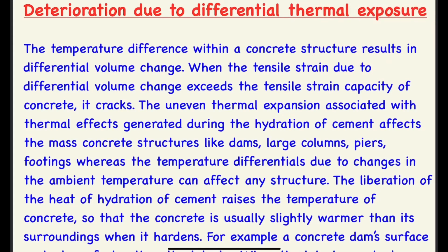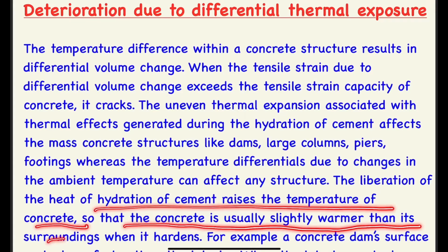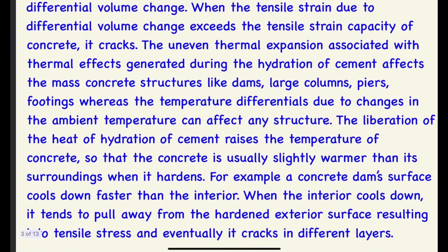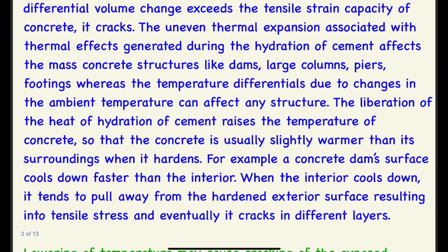So why is it hot? Because the reaction is continuously going on, and it is liberating a huge amount of heat because of the reaction between water and cement. So that is what it is telling here. The liberation of heat of hydration of cement raises the temperature of concrete, so that the concrete is slightly warmer than its surroundings when it hardens. Okay. For example, a concrete dam's surface cools down faster than the interior.